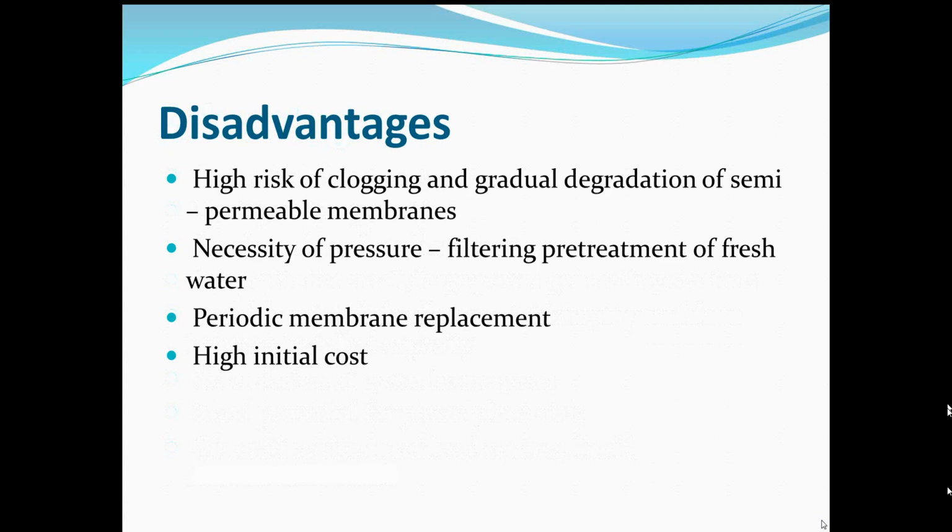Now, what are the disadvantages? The major disadvantage over here is the membrane. There is a high risk of clogging and gradual degradation of the semi-permeable membrane, because foreign particles, dirt, and dust come and clog these membrane holes, which doesn't allow the water molecules to flow across it.